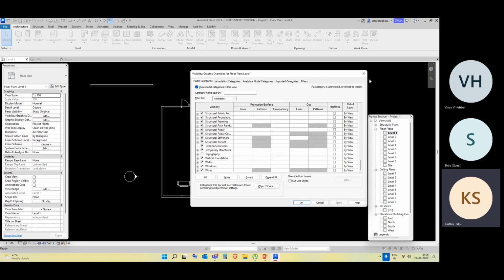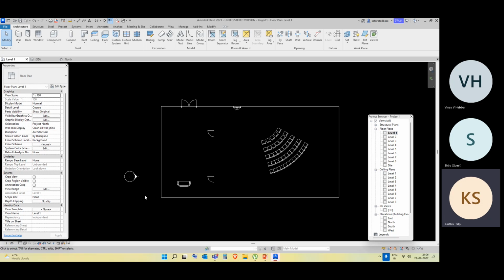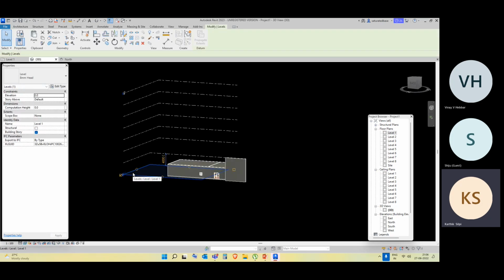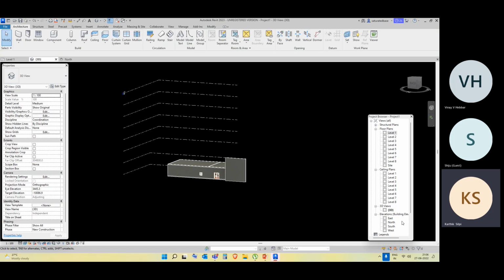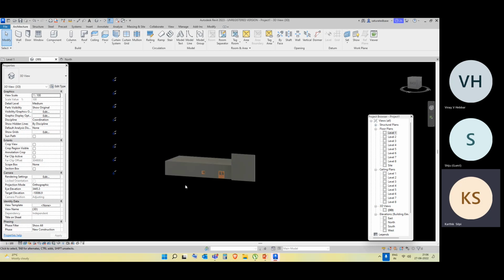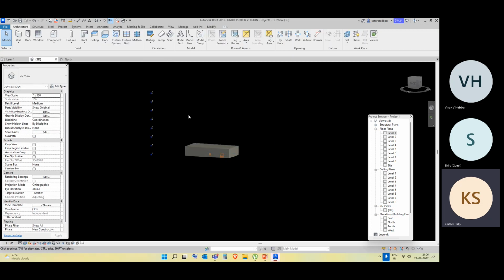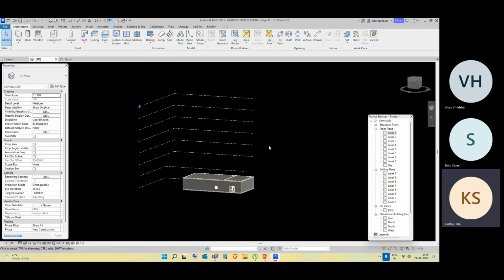Right now we'll use this a lot of times, multiple times, and we'll see what the uses and benefits of those are. So currently my requirement is to turn off these levels in the 3D view. Levels will be there in the level plans and all, but in the 3D views it is causing a hindrance for me. I just wanted to hide these levels on a temporary basis.